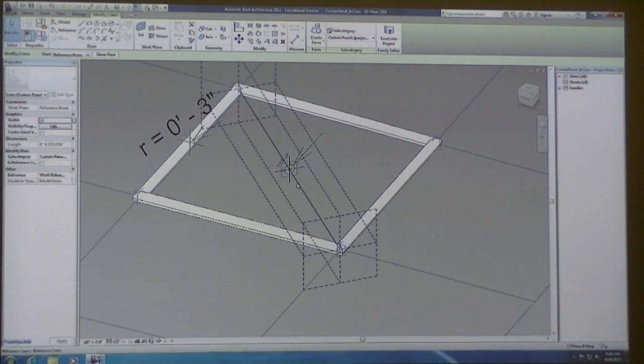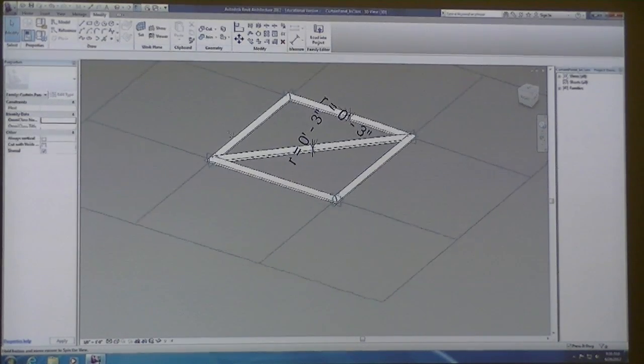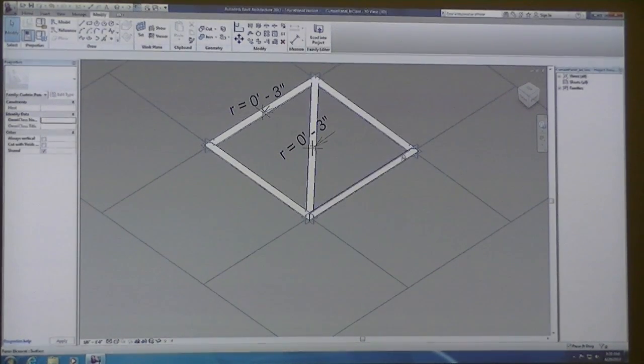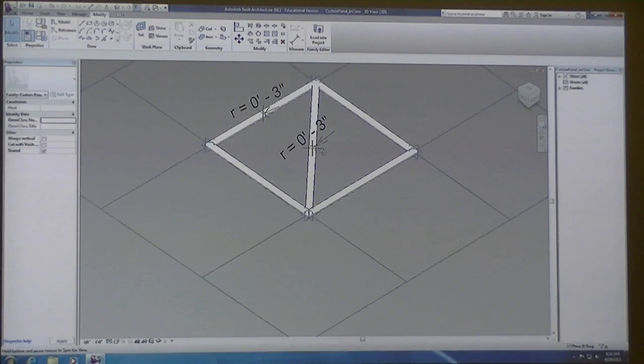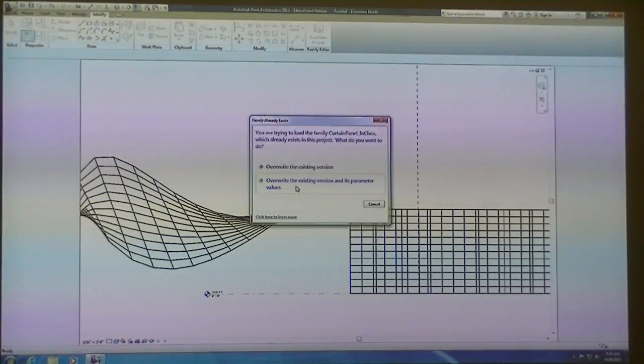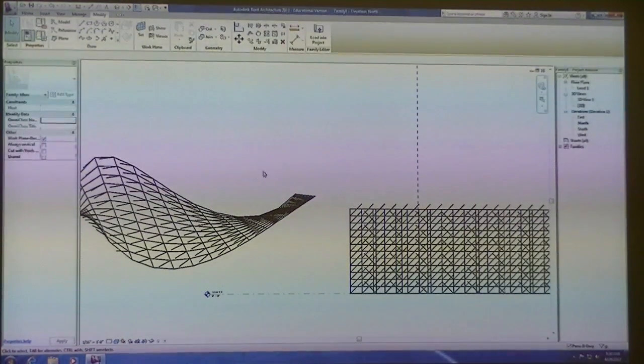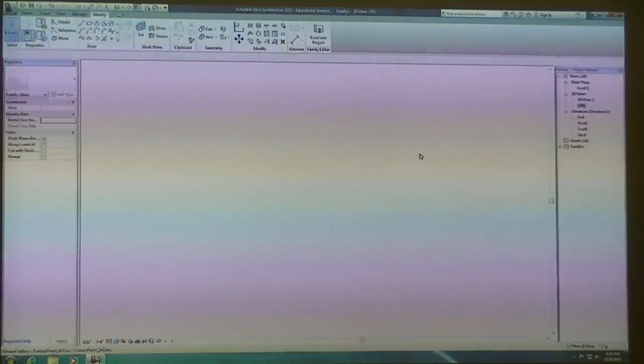And all I'm doing here in the middle is making another pipe. So those same steps that you did for the border, I applied to the center as well. And so when you're done, you can save that and then load it into the project. And because you've already applied this to this environment, you can constantly overwrite. You can add more parts to this component, and you can overwrite, and it should update all of your surfaces. And looks like I did not snap correctly.